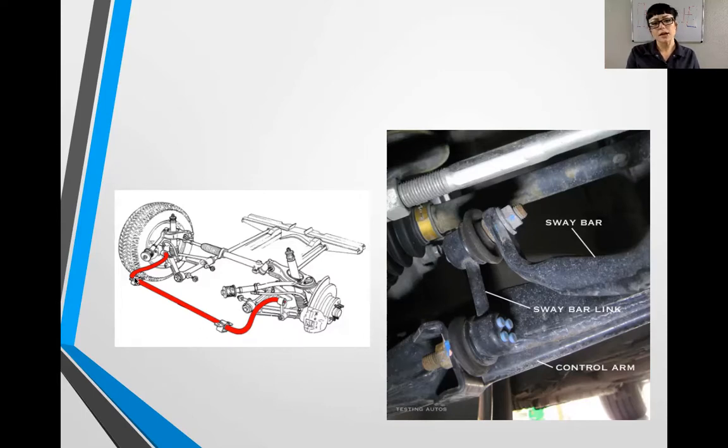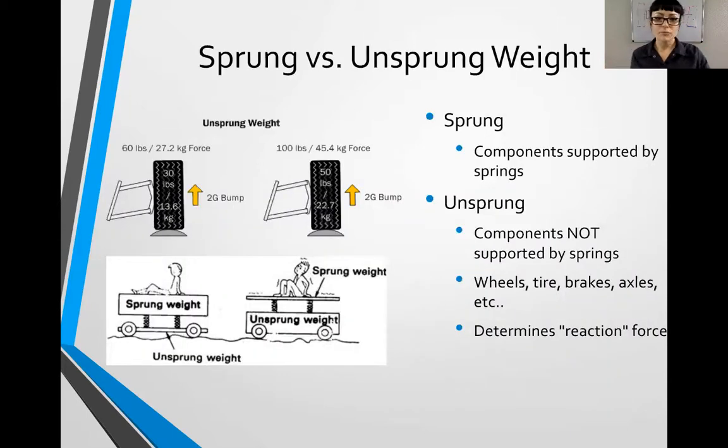We can get clunking too from our sway bar bushings. So these are sway bar bushings. If you're looking at my mouse here on the frame, these are sway bar end links. The end links may have bushings or may not. Like this design doesn't use bushings. Instead, it uses a joint type of design. So anyways, just some points to talk about.